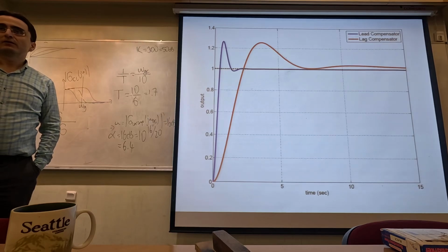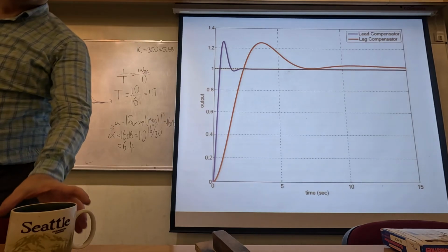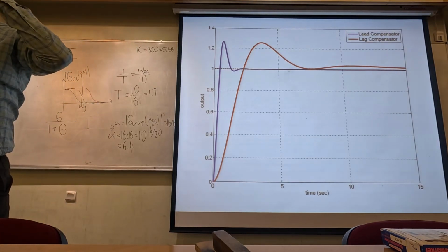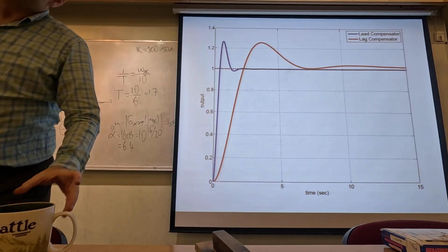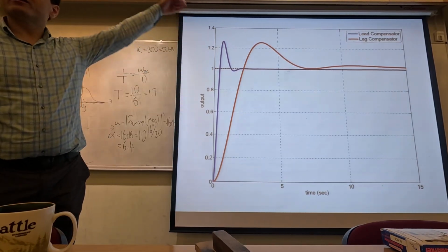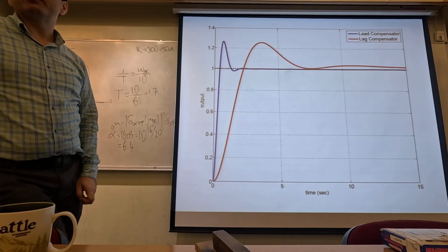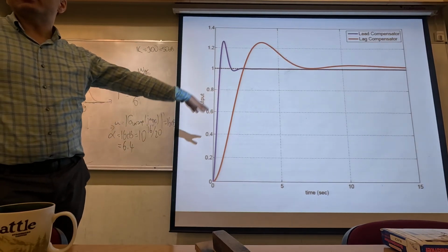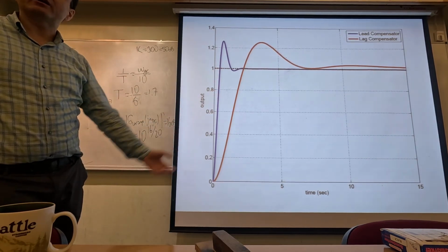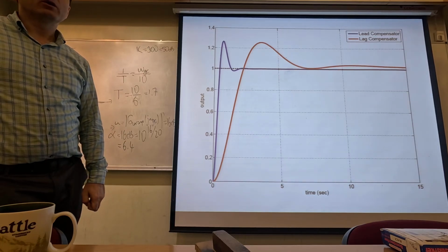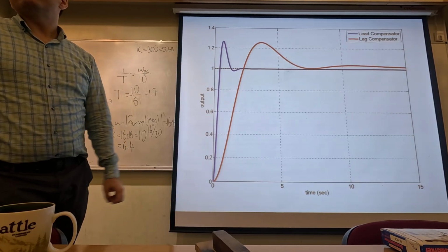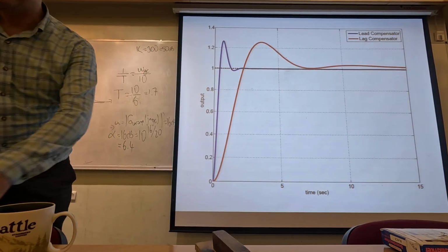There are some systems where it is really hard to solve the stability. Sometimes if the phase is, for example, decreasing quite sharply, then phase lead compensator might not be possible. Also, if the phase is not passing from the required point, phase lag compensator might be impossible. Okay? But there is also a reason related to the noise.